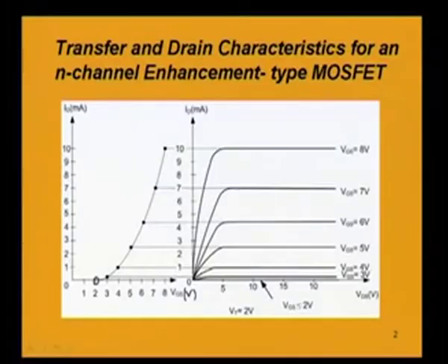That plot can be obtained by joining all the points whose coordinates are VGS and ID. So, in this drain characteristic, the saturation current is just extended, and the intersecting point between this saturation current and the corresponding gate to source voltage is the point which we have to obtain.